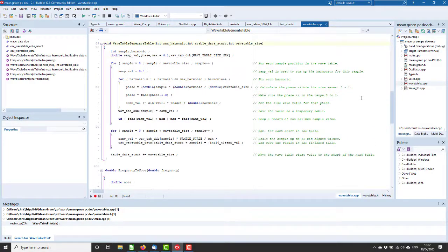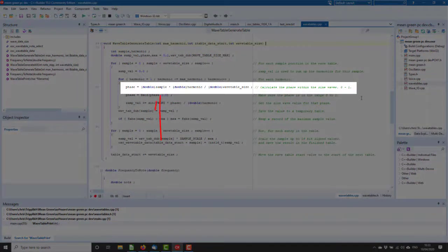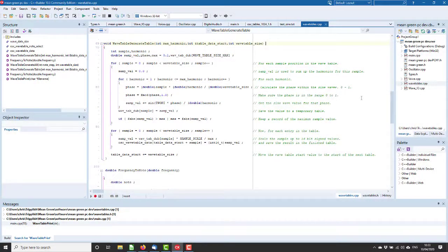Okay, and also we need to note that although we are using integral samples to create the table, here the sample could be a fractional value, so we can calculate the table value between samples and compare it to the one we interpolate between samples. This allows us to measure the noise we generate when we interpolate using this table.